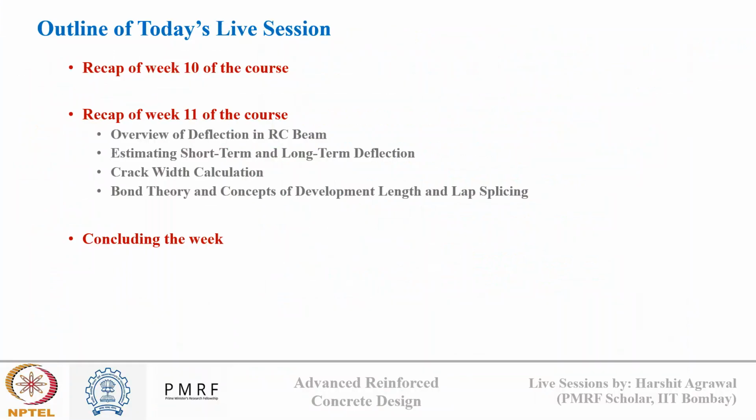So in today's session, we'll first have a quick recap of the week 10 session that we concluded last week, and then we'll review the week 11 learnings. The week 11 recordings are oriented towards understanding the serviceability criteria of design of a reinforced concrete structure. Today, we'll start with a discussion on deflection in a reinforced concrete section, considering both short-term and long-term deflection. In long-term deflection, we'll talk about the effect of shrinkage, creep, and temperature, and we'll see how IS 456 imposes limits on deflection for design purposes.